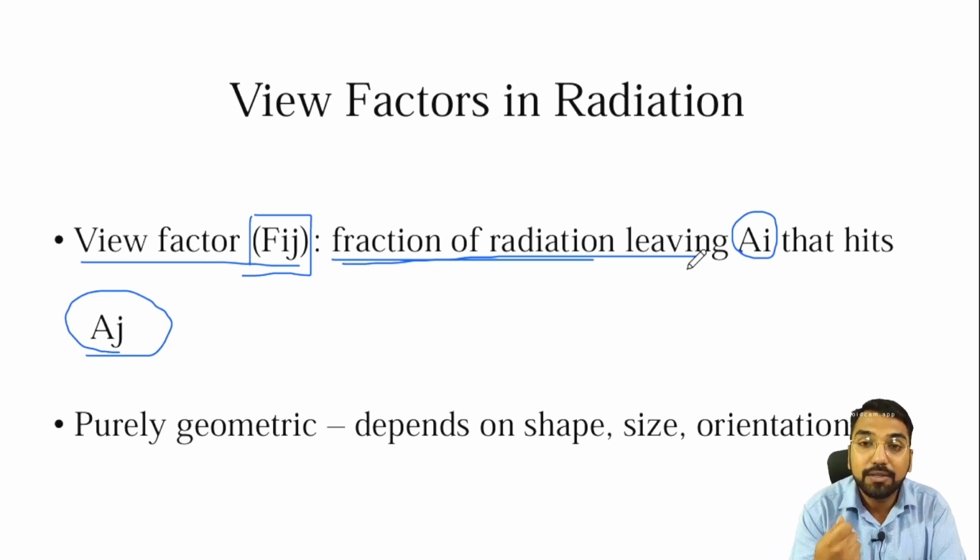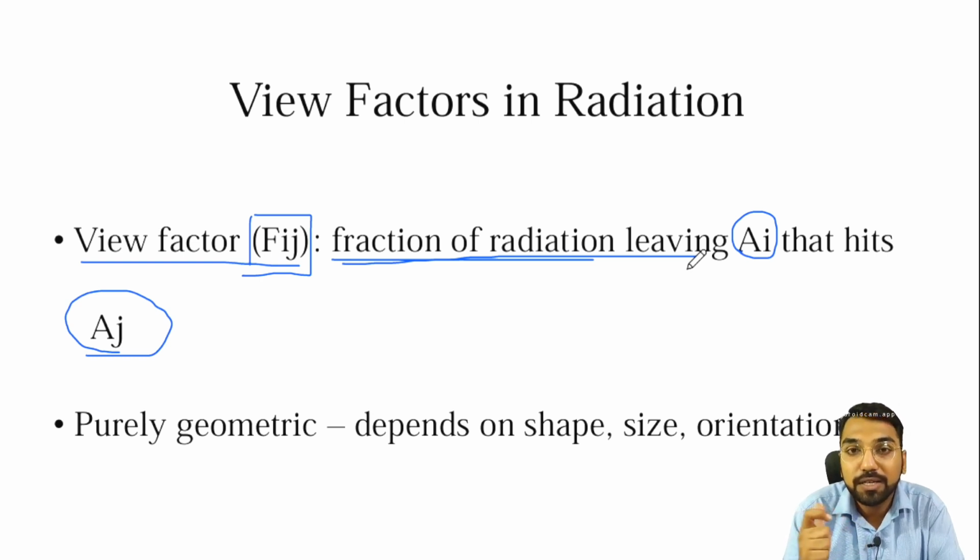And why is it so? Because only the surface area of your front side is exposed to that radiation. So that's why the view factor is important. How the energy emitted from a surface area reaches the surface area of another object is majorly important to analyze radiation heat energy in actual practice or in engineering applications.